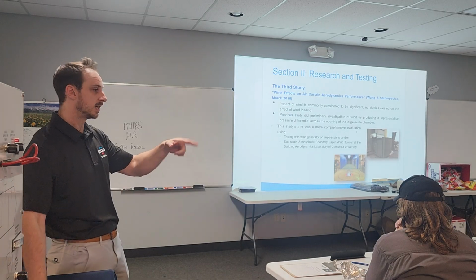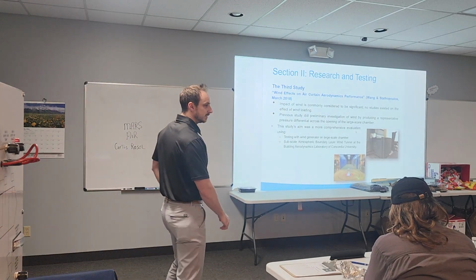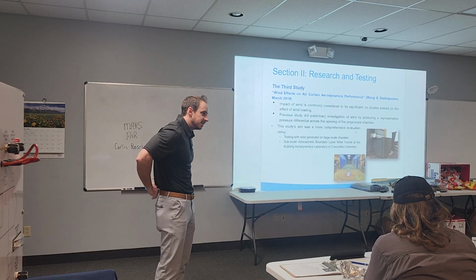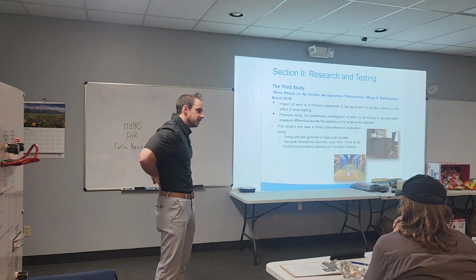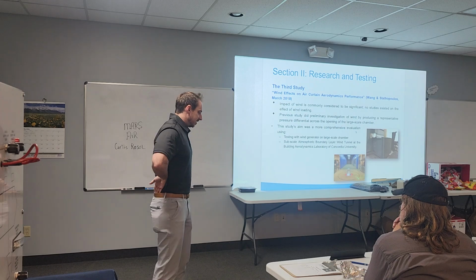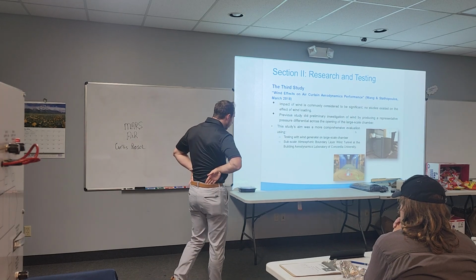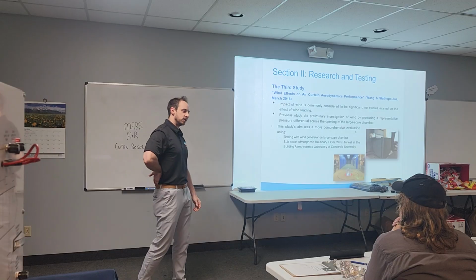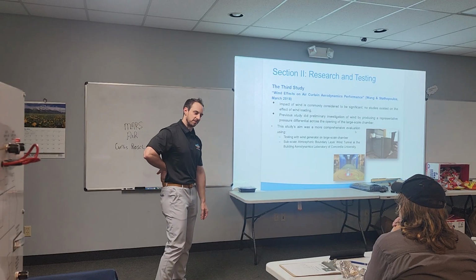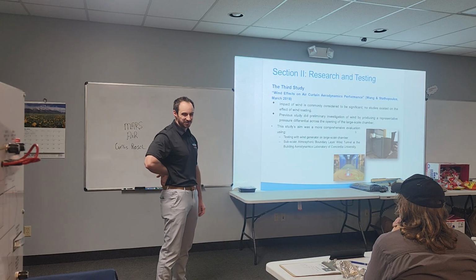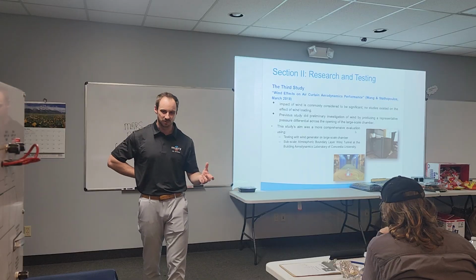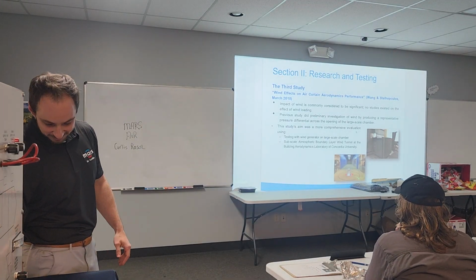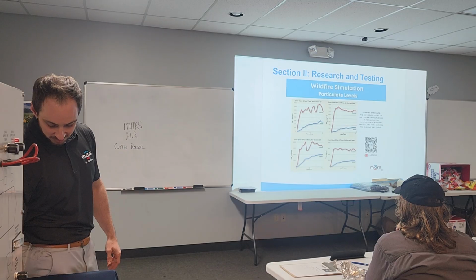Quick question, in that case we've got two doors inside the building. Could I air curtain each one? Yeah, you could, but you're saying if both are open? Yeah. No, unfortunately, it would still create the negative pressure. Too much negative pressure, okay. Yeah, and like I said, what they can overcome is very slight. So it would be nice to be able to do that, but unfortunately we're unable to. Okay.